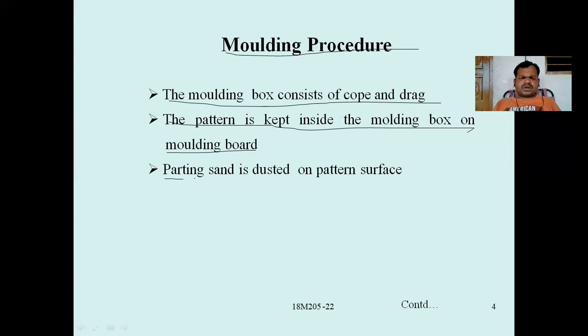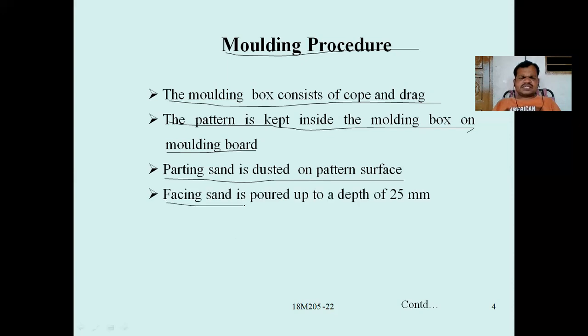Next, parting sand is dusted on the pattern surfaces. Next, facing sand is poured up to a depth of 25 mm.